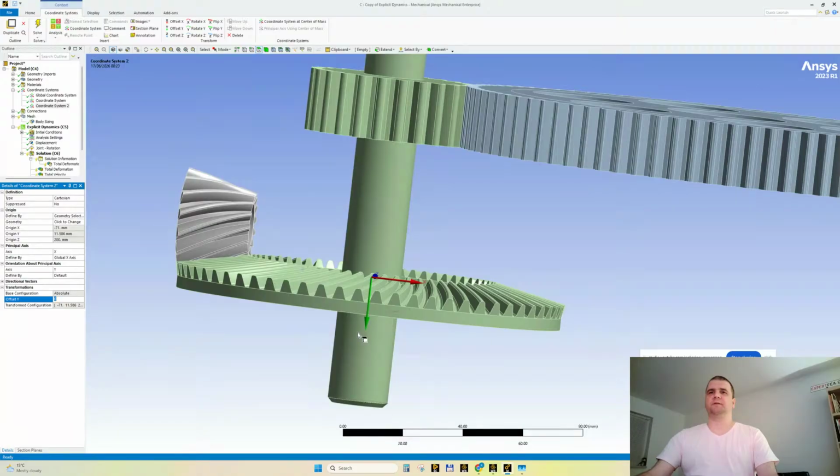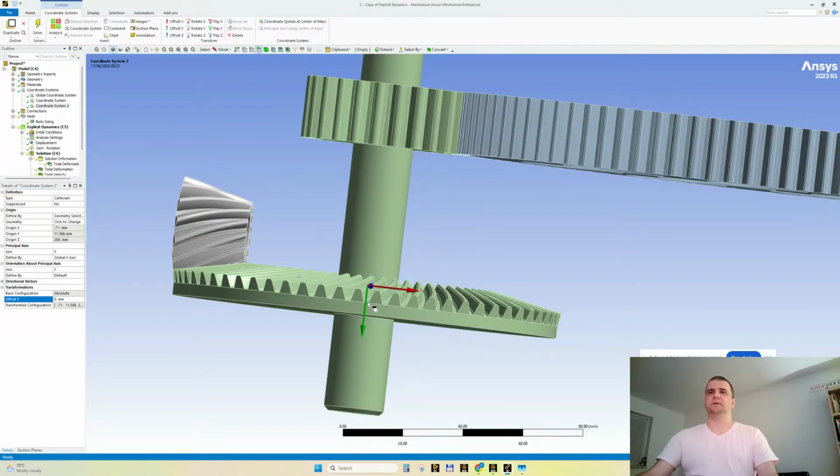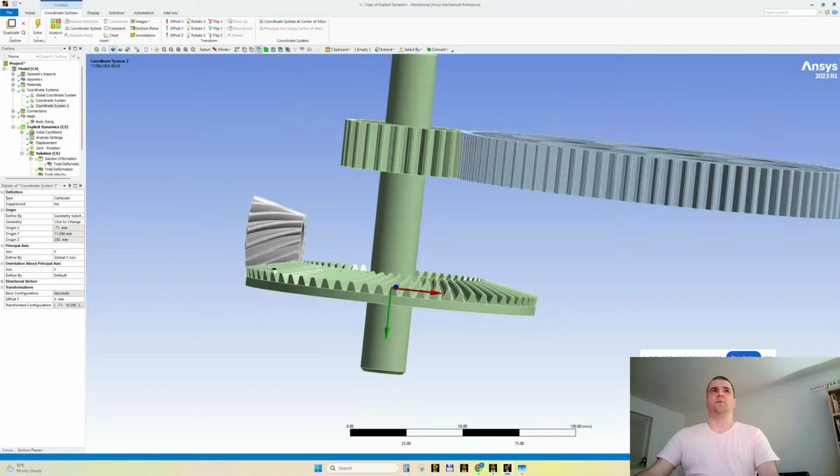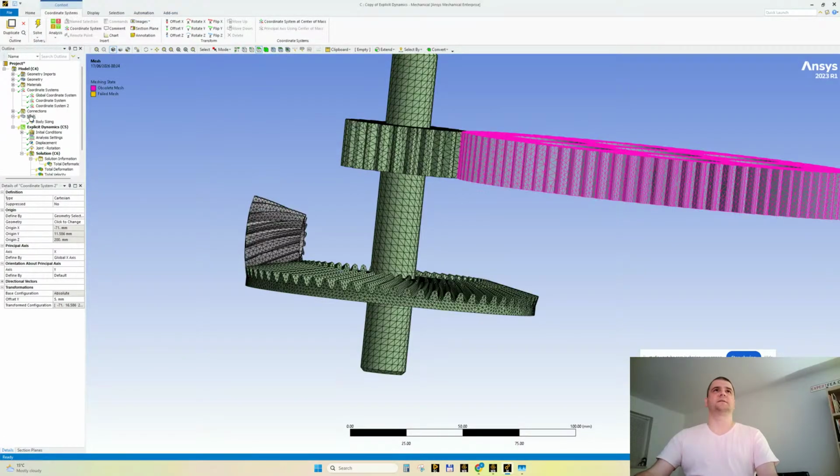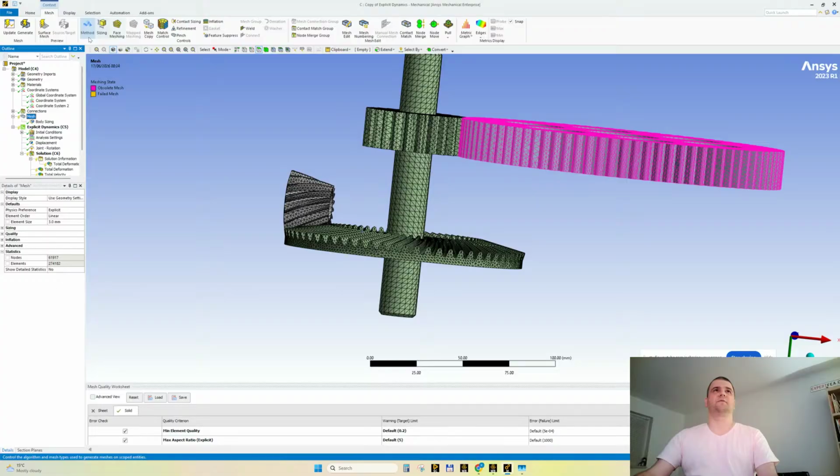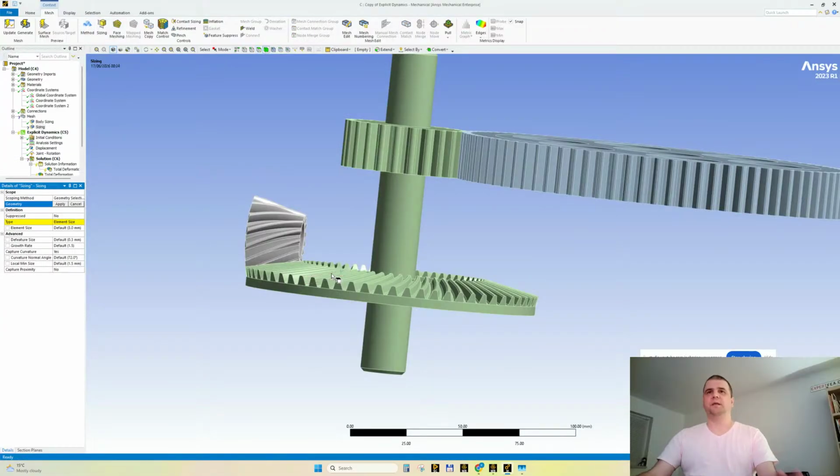Maybe around 10 millimeters to move it downwards, let's say. So 10 millimeters. It's kind of too much. Let's make it 5, and this is all. So I will use this again as a sphere of influence for this sizing. Control B for it.